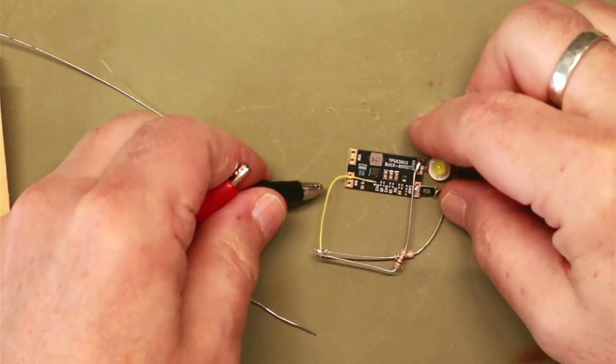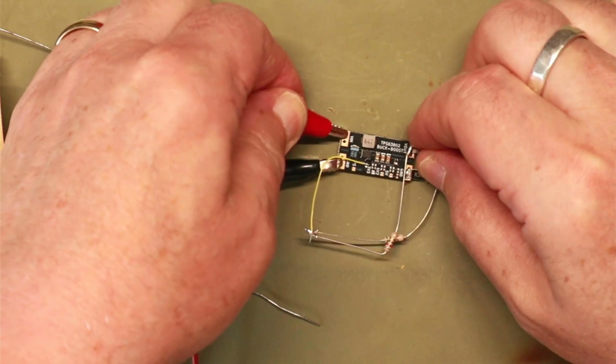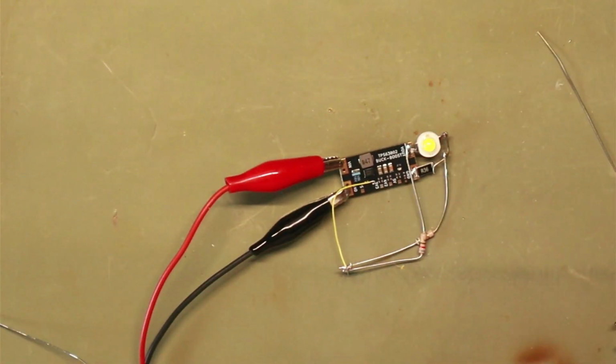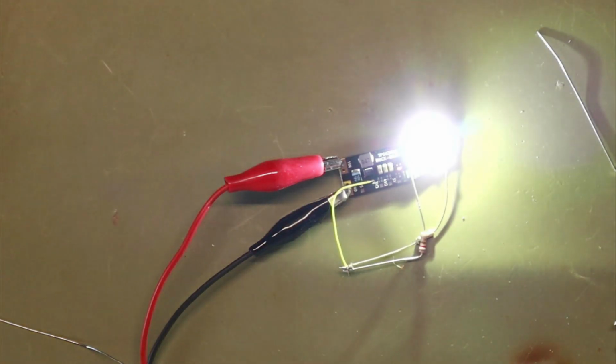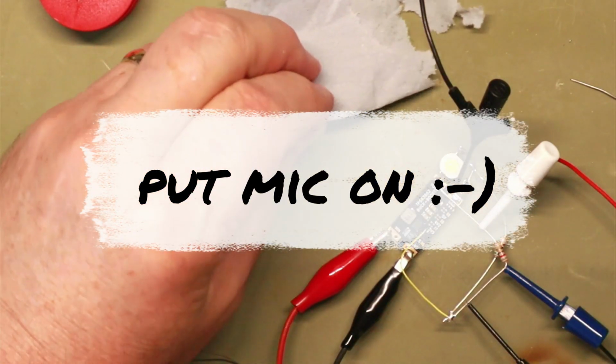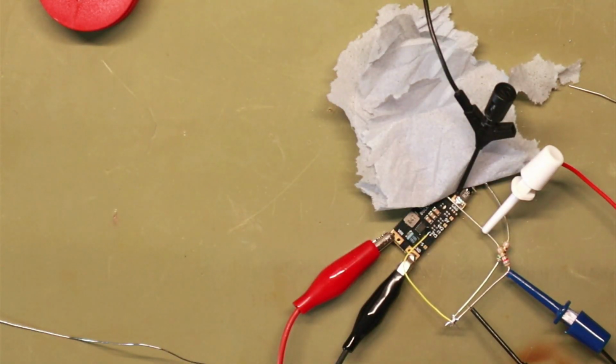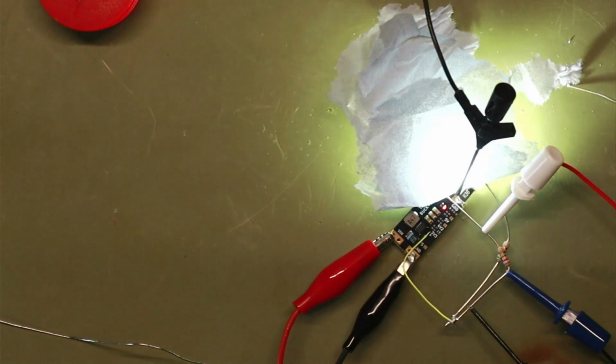So power supply set to 1 volt. Put it on here, onto here. Turn the output on. Whoa! Wow! 2.2 volts. I'm going to put a bit of tissue over here, just so that it covers the light up. It's a bit bright. We'll put power on. This is running at 3.2 volts going in. You can see how bright it is, and that's pulling 0.6 of an amp.